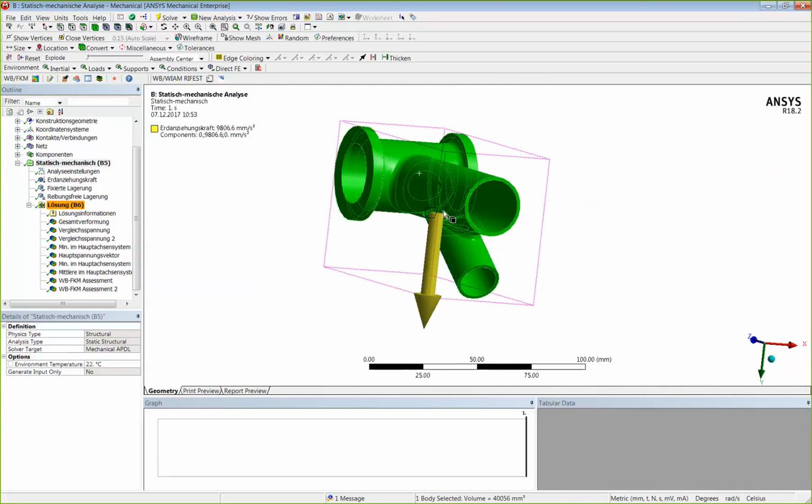For structures like these, the guideline said, okay, we could take the volume, which would be 40,000 millimeters here, multiply that by 4, which would be 160,000, and compare that to the surface, which would be 31,000. So I would have 160,000 divided by 31,000, which should be around about 6. And then I have an estimate of how this characteristic length could be. If we have a clear cross-section, it's more likely that we could directly have a characteristic length from this cross-section. But usually we go for this point, because our parts are simply too complex.